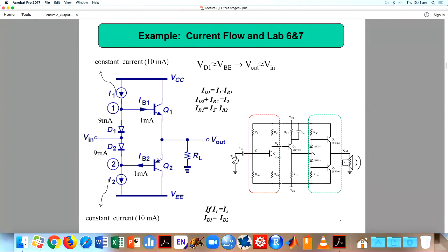So you got two transistors, same push-pull. Now you got a current source here, and a current source here. This diode is for biasing Q1, because when it is on, you get around 0.7 or 0.8 volt depending upon the diode drop. That is used for biasing Q1, and this diode is for biasing Q2 when you don't have any signal here.